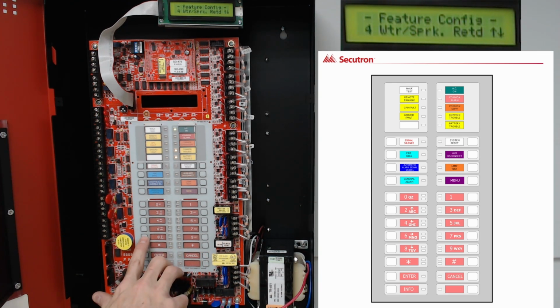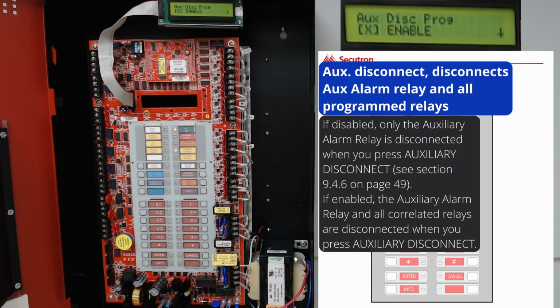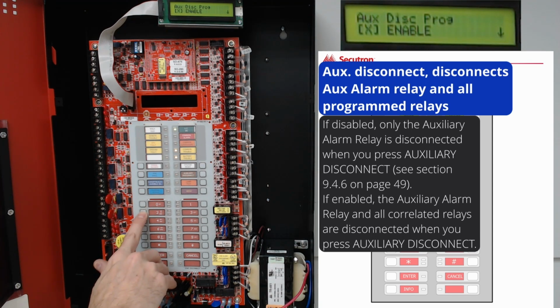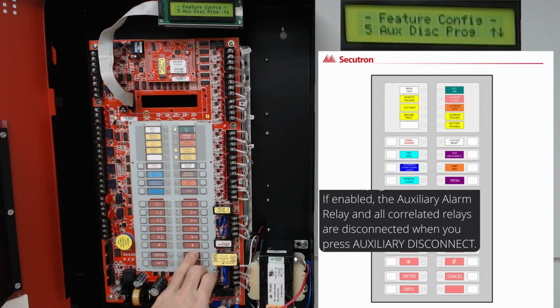Our next Feature Config option is Aux Disconnect Programming. By pressing Enter, we enter into its options. By default, it has been enabled. If we'd like to change that, we'd hit the down cursor arrow and then the left or right cursor arrow to apply the X. We can then press Cancel to exit back out to the Feature Config options.